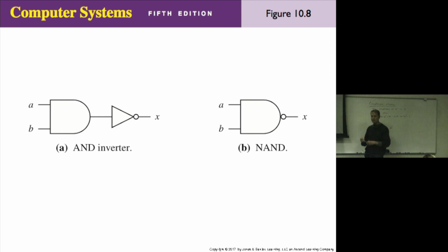That has tremendous practical implications for digital logic design. Are you with me on that? Because you have to throw in an extra transistor. You can make a NAND with fewer transistors than with an AND. That's an engineering fact of life.